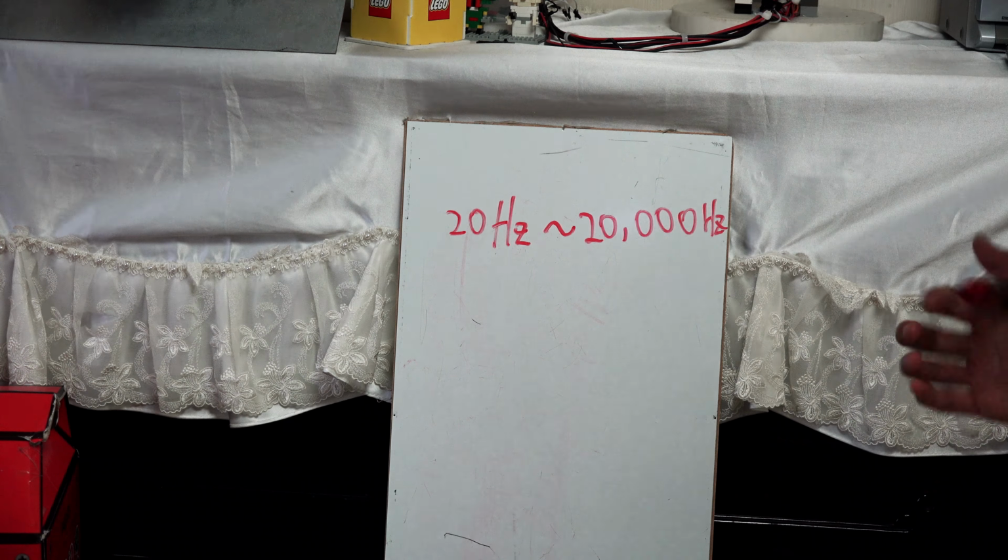On this echo pin, after shooting, we can measure the duration. It is just low. We can digital read it with Arduino, and we can read low, high, and low. We can find out the duration of this with pulseIn, which is in the Arduino library.